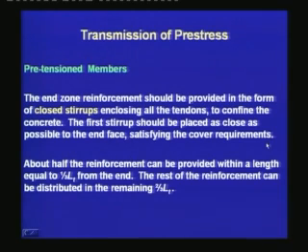As we had seen from the variation of the transverse stress, it is maximum at the end, and hence the first stirrup should be placed as close as possible to the end, and the stirrup should be closed, which confines the concrete and helps to check the formation of splitting cracks.